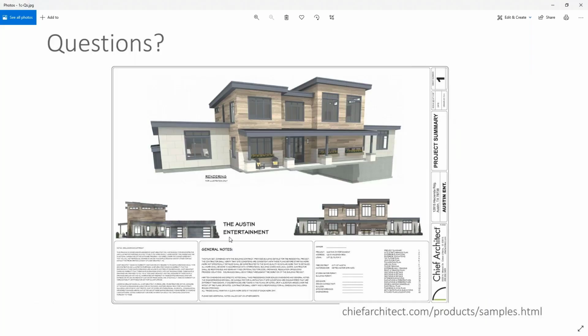Scott, we have several people writing in asking if you could demonstrate how to create a panelized appliance. Okay, so there are a few options when you create a panelized appliance. A lot of times what I'll do is just use a cabinet. So whether it's a refrigerator or a dishwasher, I will just mark that cabinet as a dishwasher and then leave it as a door or a drawer.